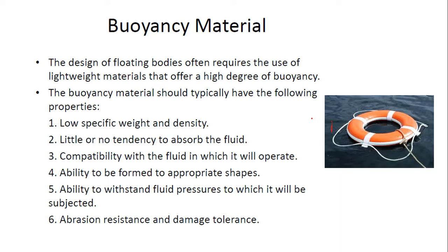So you must make sure the material is not reactive with the fluid, and its ability to be formed to the appropriate shape, whatever shape you want. It can be formed, withstand fluid pressure, okay, because this has a buoyant force, the pressure, so it must be able to withstand, and abrasion resistant and damage tolerance.